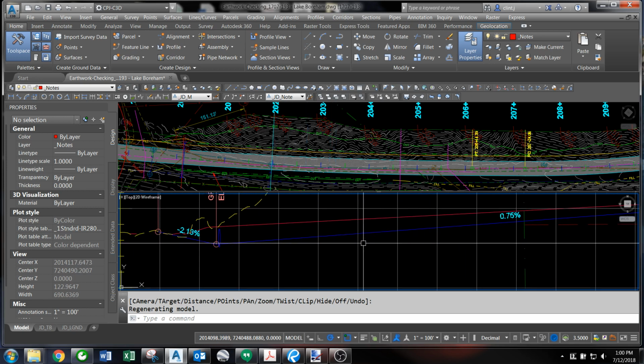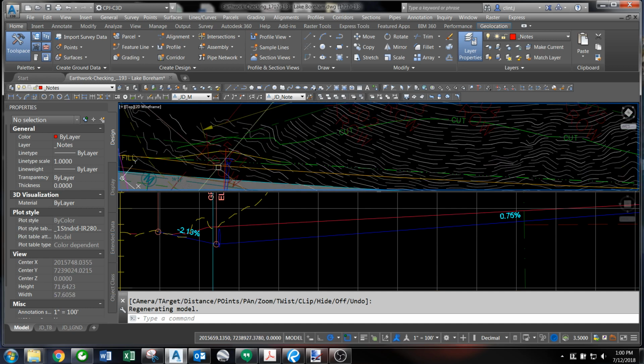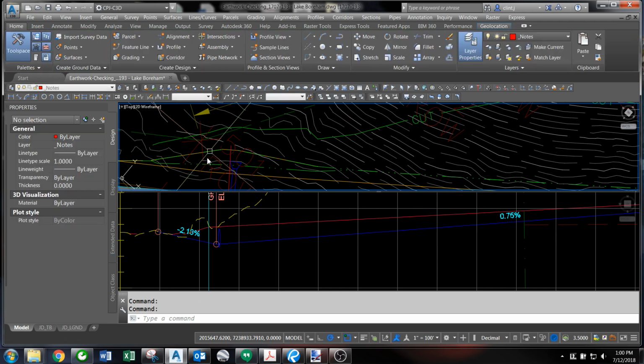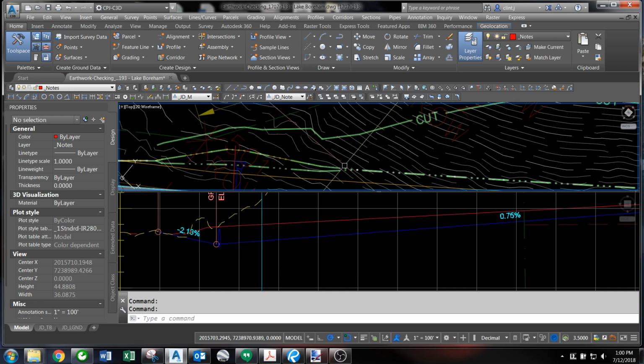So you can see that divergence there. By the time we get down here to the culvert, you can see we've designed these inlet basins where it actually opens up, and this is where the ditch is essentially the deepest.